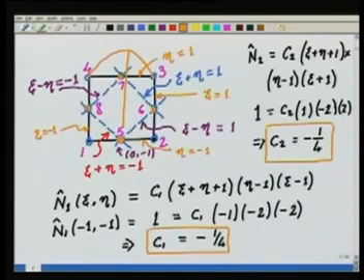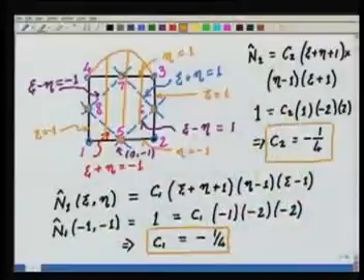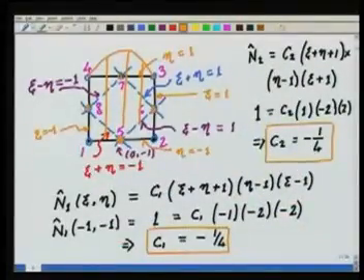Okay, so this is how our n7 is going to look. If I have to make my n7, it should be 1 at this point, and it should vanish at all other points. So how is it going to happen? You see that n7 is sitting on this edge. So if I take this edge and this edge, the equation of these three edges, multiply them together, then by definition this function is going to vanish on this edge and this edge.